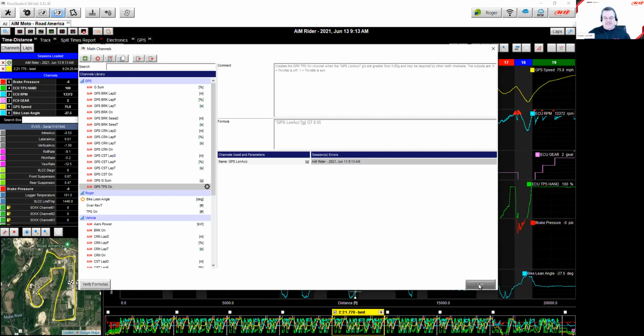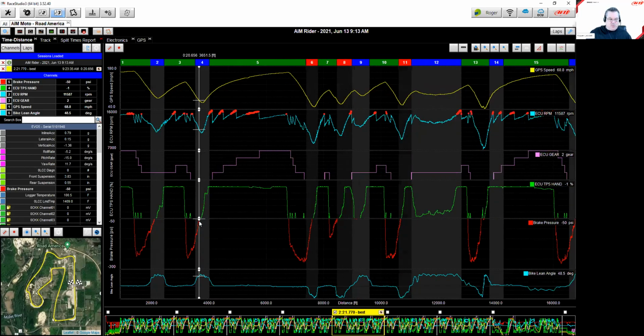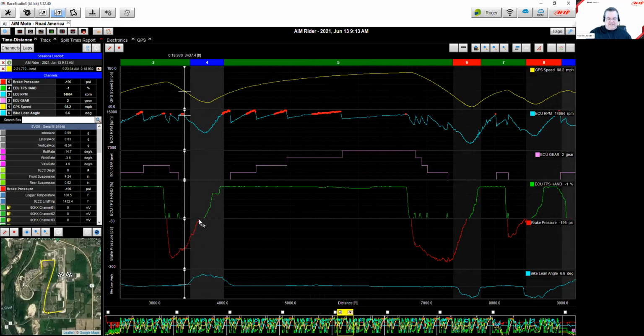Perfect, but this is a visual representation of a rider that is coming off throttle and going right to brake pressure, right? So we can see it visually. What we can't do is do math on the time that the driver did that. And I'm just going to zoom in on this one right here, just because visually I see that there's a disconnect between those two lines. That is what we're looking for, right? That is tiny, and it's in the middle of a corner. So he's waiting. You can see by the lean angle here, and he's coming down right here at the apex speed of the RPM and the speed and full lean over. Of course, he's going to pause there just for a little bit and then take off. Not saying you should never do that, but that's visually what you can see, and then that would focus you into an area where to go look a little harder.